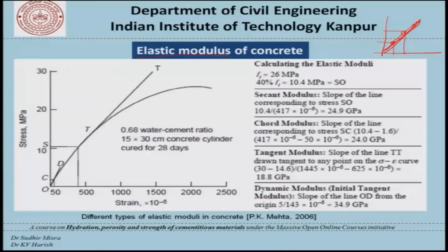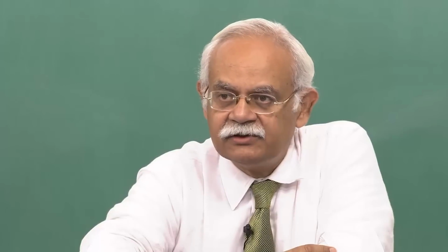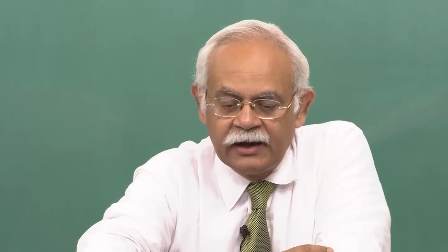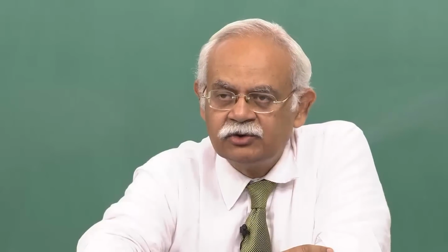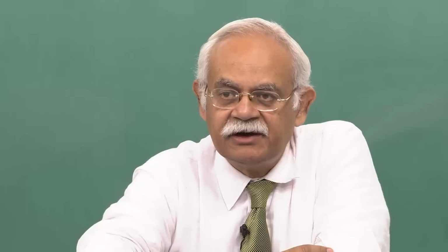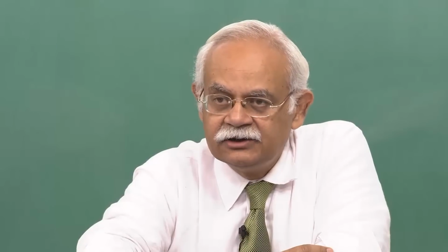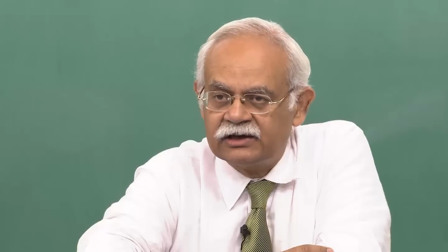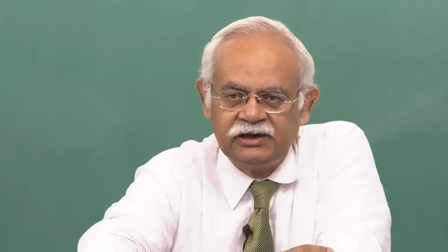In the case of a non-linear material like concrete, as we see here, the stress strain curve is changing its slope at different levels of the applied load. In a situation like this, how should the modulus of elasticity be defined and used as far as calculations are concerned for deformation, deflection and so on?